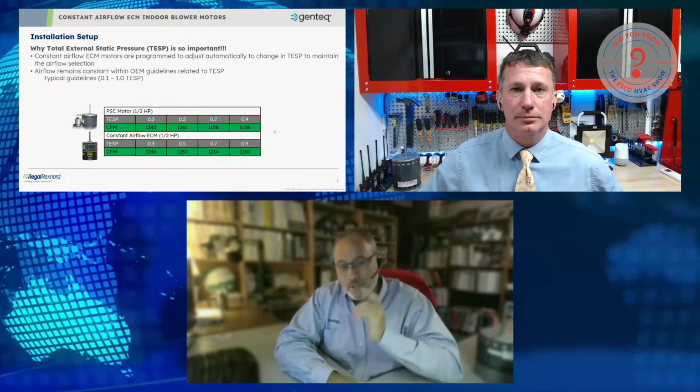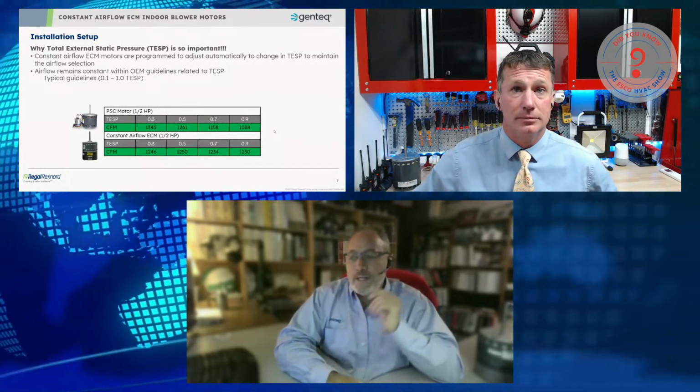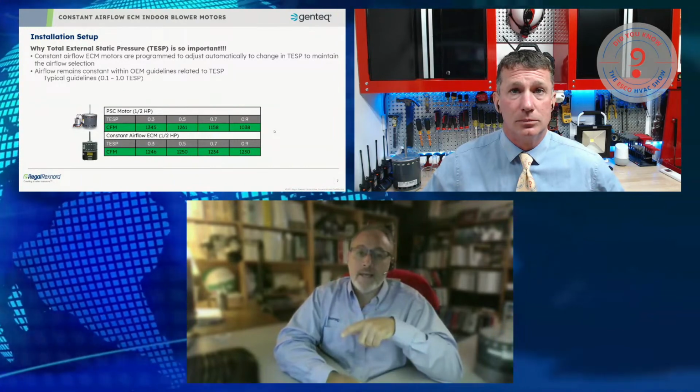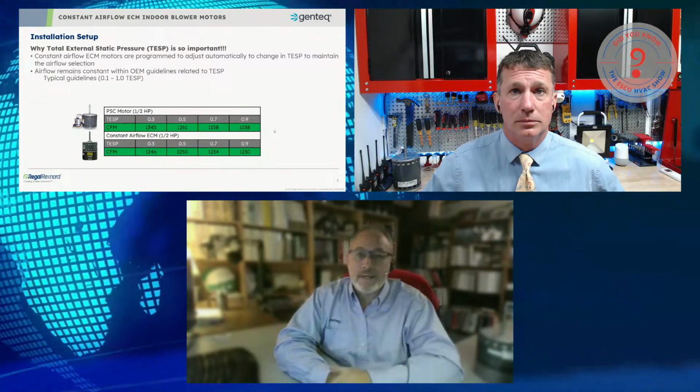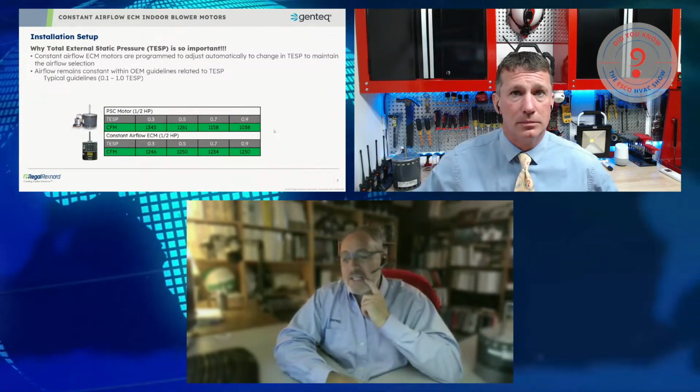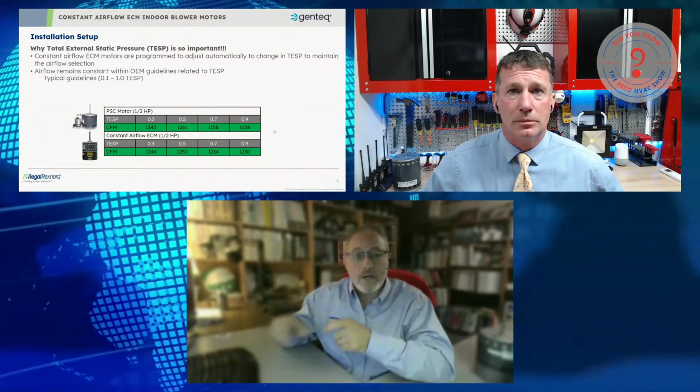They have a speed limit built into them, and the speed limit's going to be based on static pressure. So does the motor know static pressure? No, but it knows how fast it's running. Exactly. So we let the manufacturer of the appliance dictate where that speed limit kicks in. And so everybody always asks me, well, when's that speed limit going to kick in? And I say, look at the charts.